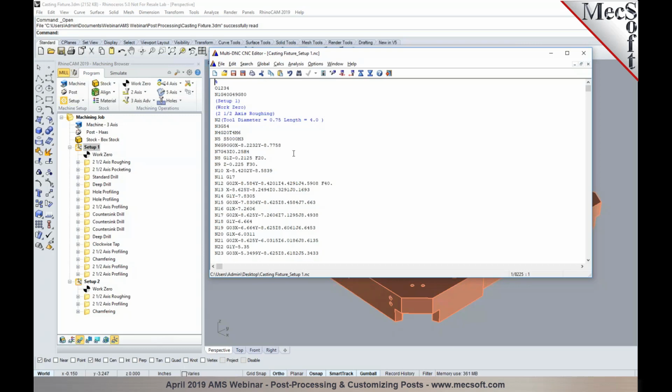But having said that, typically most G-code editors or DNC programs will take the file name as a command line argument, and so you should be fine. So in case you do run into this, that's probably the reason why it's not loading that G-code file. I hope that makes sense.